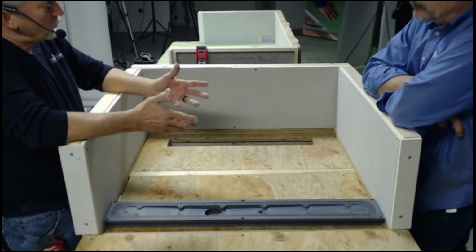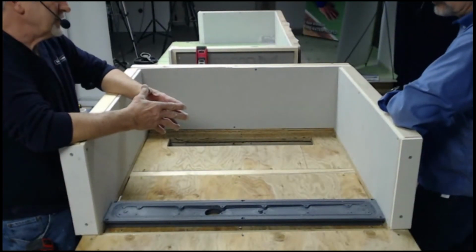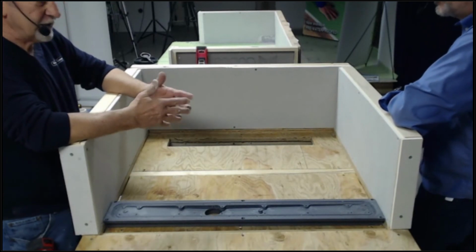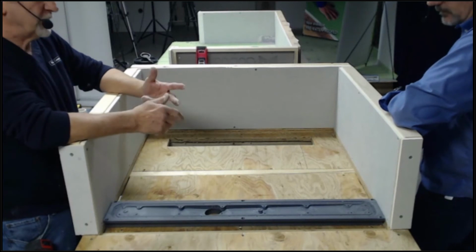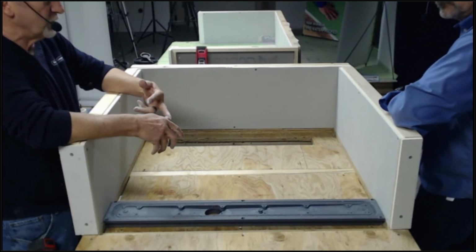Right. So if your floor joists are running perpendicular to your drain, then you're not going to have that opportunity without cutting into the floor joists. And then again, you've got structural issues. On multi-units, you're going to have to get an architect or structural engineer involved with that.